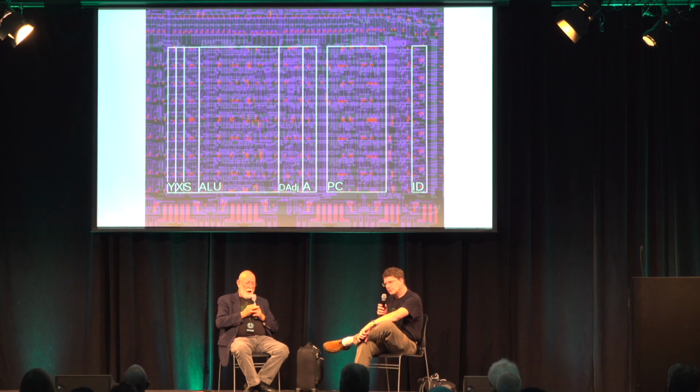And so we had a special bus over here. We had the data bus, the address high bus, the address low bus, and then a special bus. If you're going to do an increment of an address, you bring the X or the Y over to the ALU, because that's where you're going to increment it, and you bring the program counter this way. So we had to look at how many lines we had to go, and if you saw the flow chart, you'd see how we were transferring things in each of the timing states. So that's what we did.